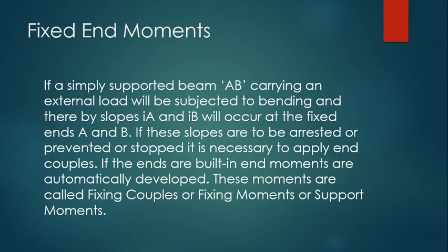Next, we are going to discuss fixed end moments. What are fixed end moments? Due to fixity of both ends, a resisting moment will be developed at both ends based on the loading. This is responsible for making zero deflection and zero slope, and minimizing the overall deflection even at the center.